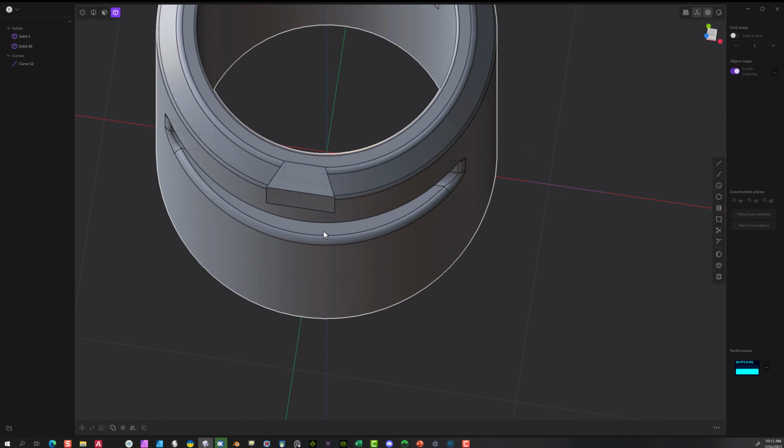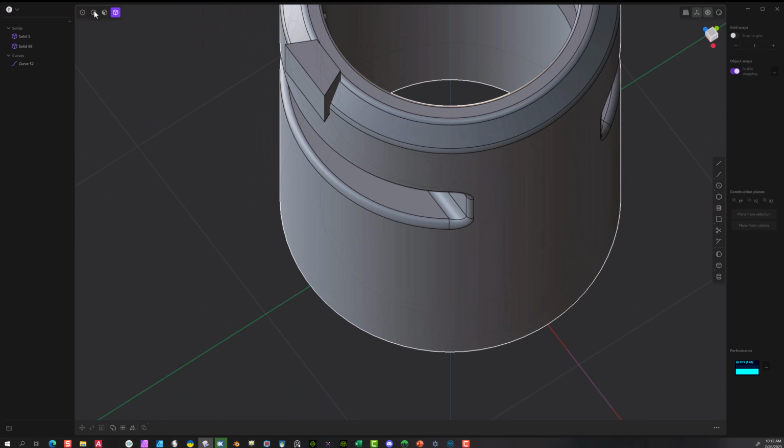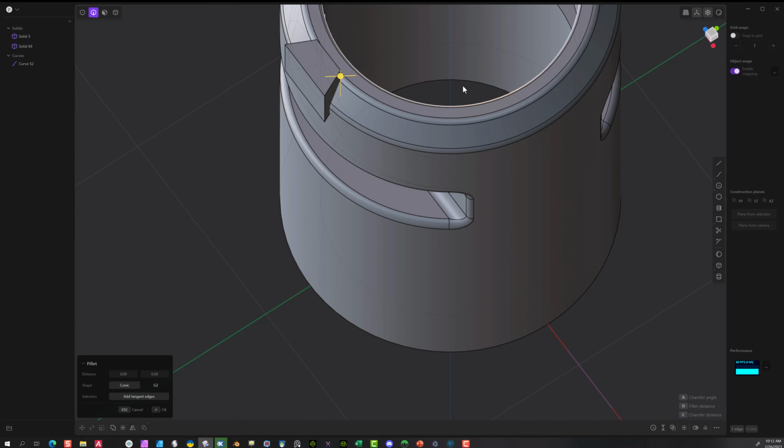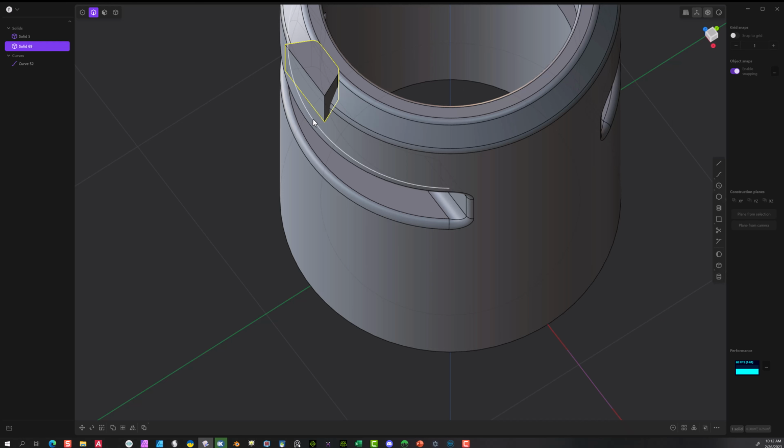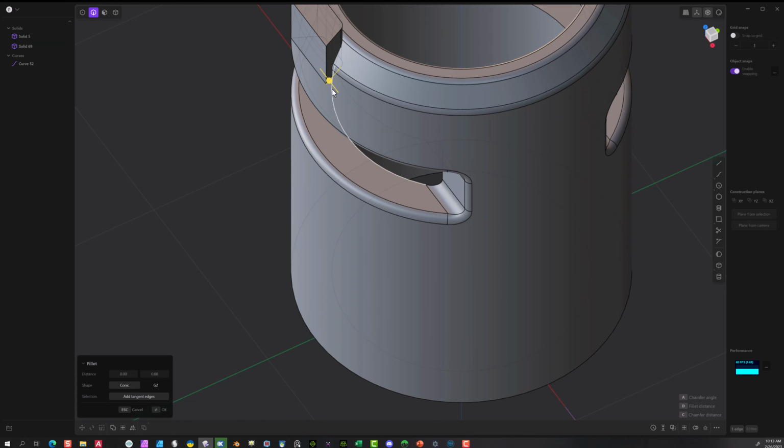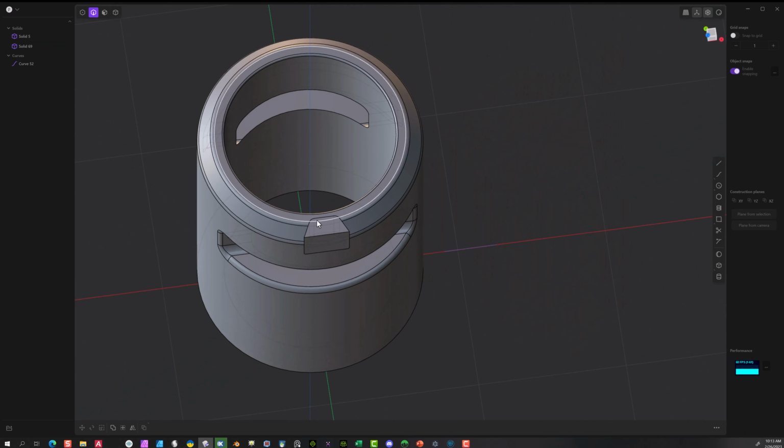Now, first of all, let's do this before we go there. Now I'm going to select the edge tool in here. And one thing I have is the see-through set up, so you can see what you're doing. Hit both of these. Now let's rotate it around. Make sure it's in the plus, that way it's a nice curvature. Let's say OK. And I've done that. It'll save a lot of time down the road. Another thing is I'd like to do the bottom too. So let's just do this. Curvature. Okay, gives it a nice round look. All right, there we go.